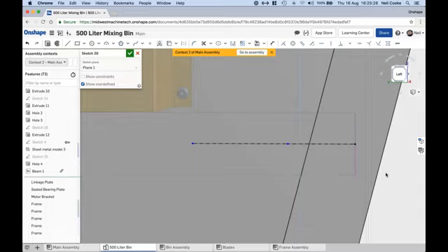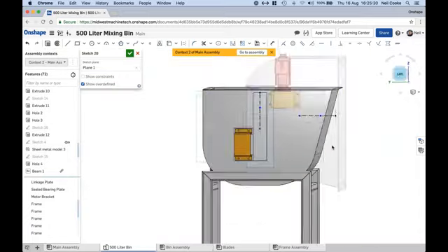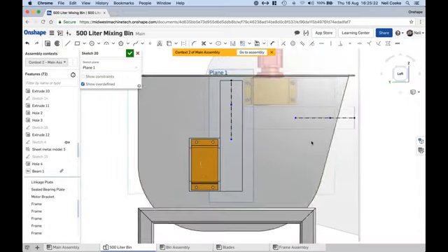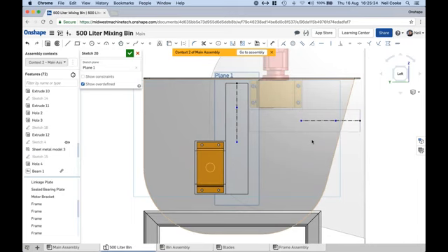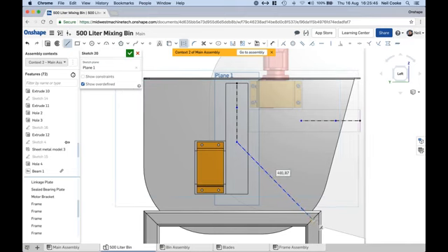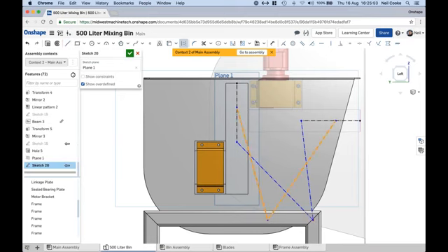You might be able to make that out, which is a reference for the context. Okay, and the last thing we'll do then is just build the linkages. Now I know from my original napkin sketch that these linkages should be crossed, so I'm going to do one there and one to there, and then one over here and one over here. Okay, so that's the two linkages in the two positions. Make those two equal. Make these two guys equal.